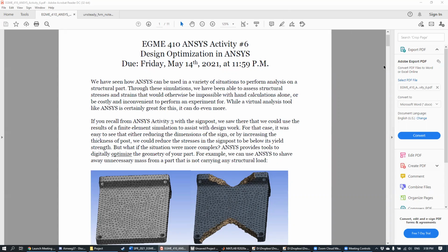No, I think it's always good to check that. Yeah. And so, if you check those reaction forces, you should get something similar to what you would get from a free body diagram. And so, yeah, absolutely. I think that's a great way to check simulation results.